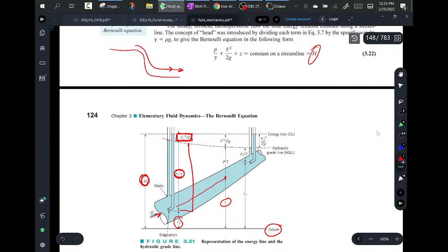Well, the Z went from here to here, and so the pressure, guess what the pressure did? It declined a little bit. So the distance from here to here, a little smaller, and guess what happened here? The area got smaller, forcing the velocity to get a little bigger. So its velocity became larger here than here.